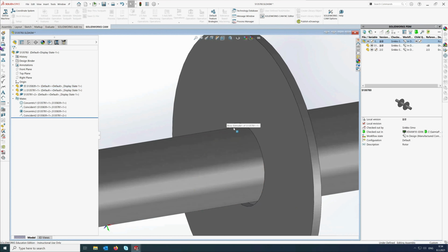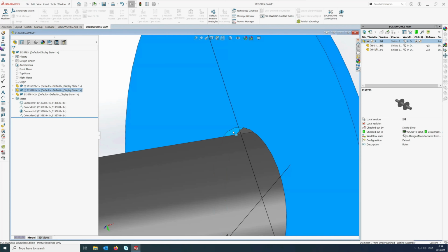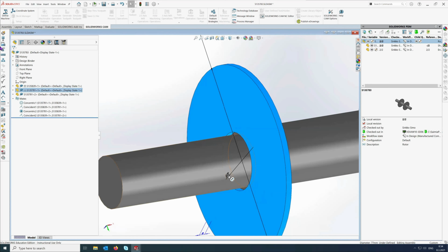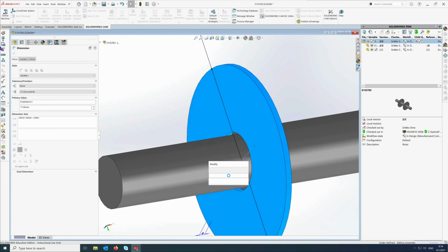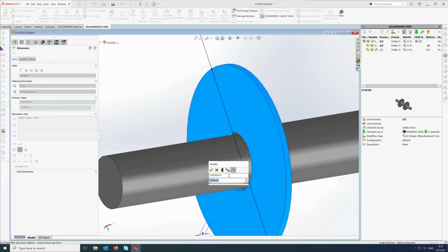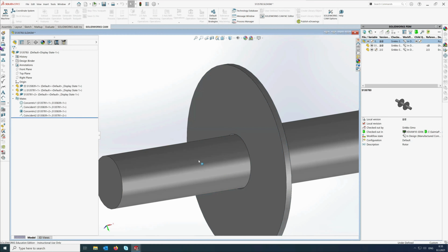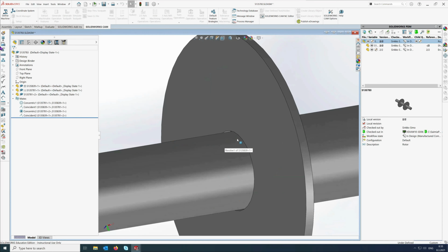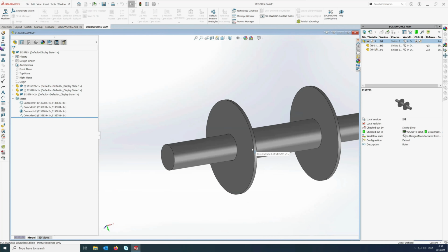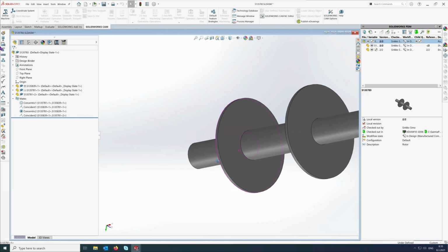So I will also modify this to be smaller, not 77, but for instance 72. So that it will be 2 millimeters more than the shaft. It means that it is still easy to slide, but the gap is not so huge.